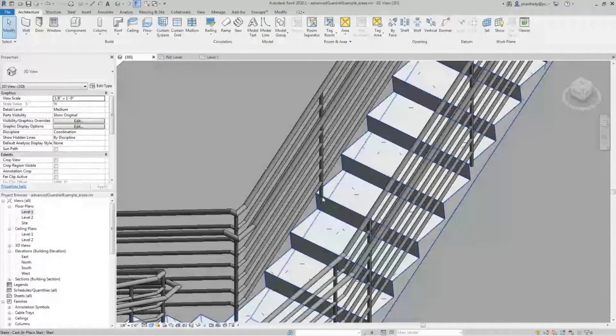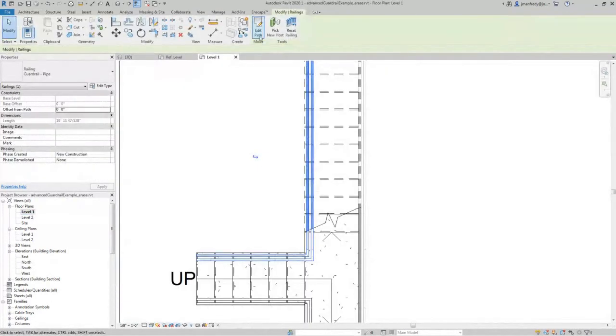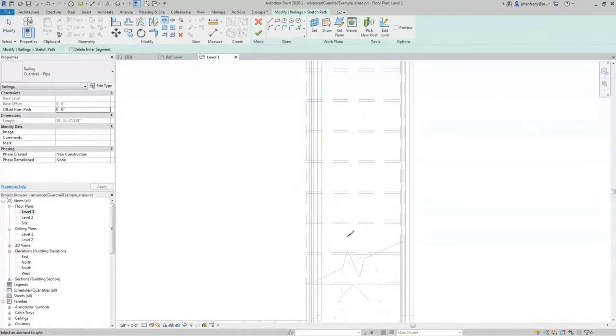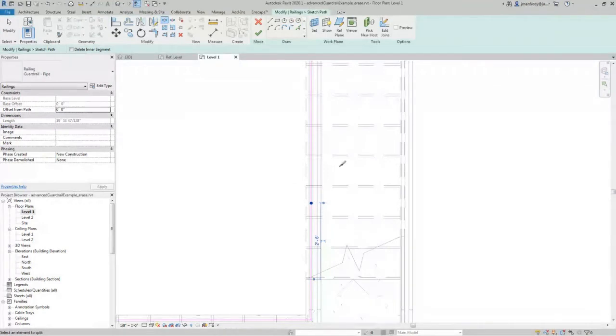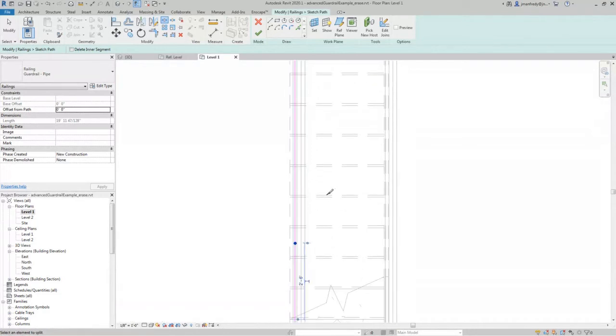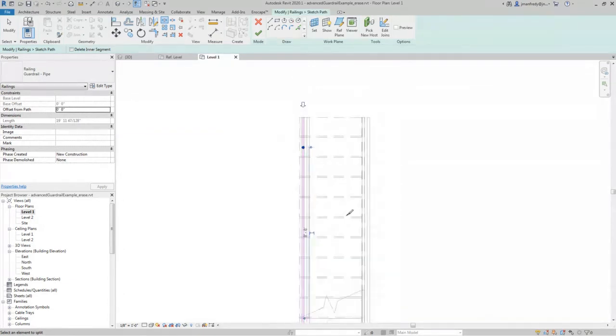If you don't like the spacing here, which doesn't look quite right there, you have to click on this railing and modify the spacing by duplicating it and changing the spacing to be further out than 4 feet, because that's 4 feet. Or, as I mentioned earlier, click on the path of the stair and use this command here called split, and split it where you want it to be. Maybe every 3 stairs I want it cut, like maybe I want one here. 1, 2, third step. Click. That's where the post will be.